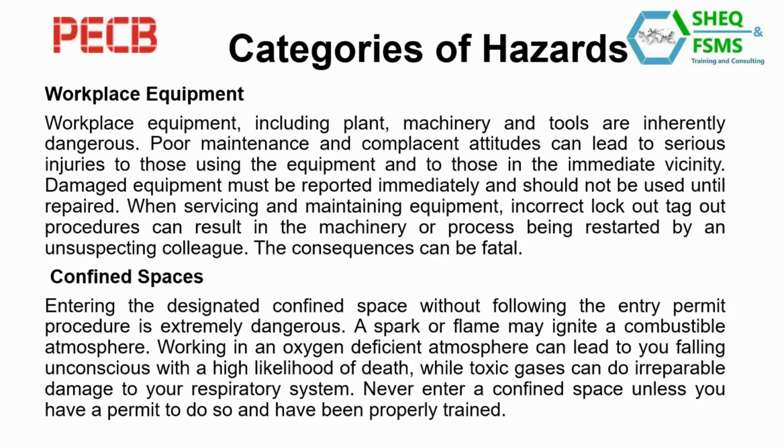Confined spaces. Entering the designated confined space without following the entry permit procedure is extremely dangerous. A spark or flame may ignite a combustible atmosphere. Working in an oxygen-deficient atmosphere can lead to you falling unconscious with a high likelihood of death, while toxic gases can do irreparable damage to your respiratory system. Never enter a confined space unless you have a permit to do so and have been properly trained.